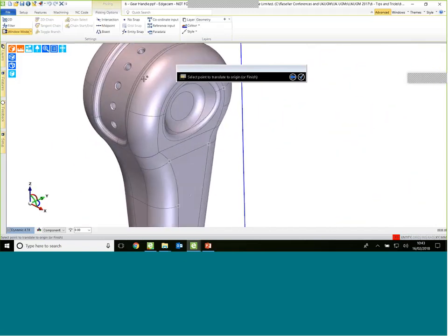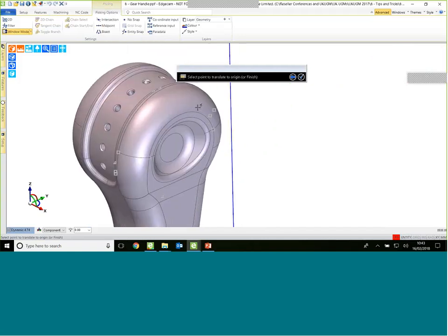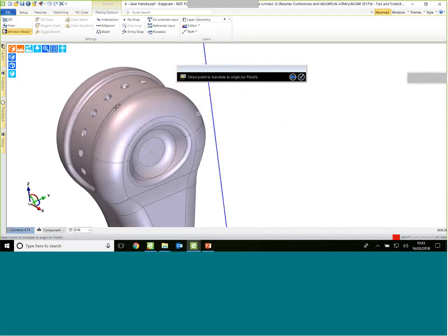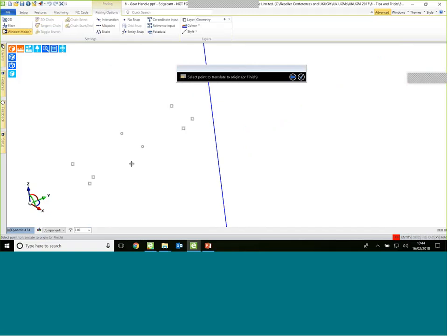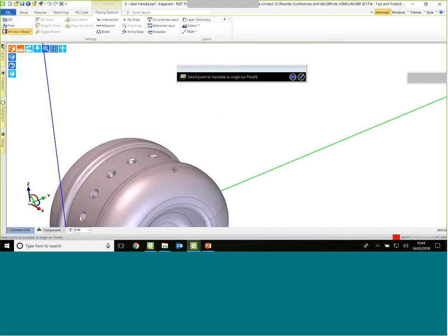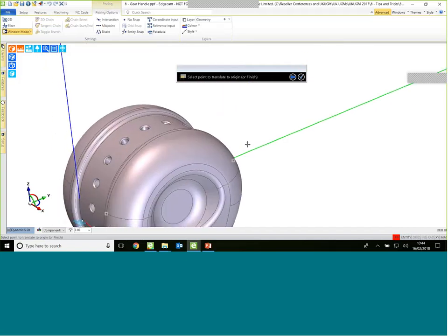It's quite annoying when you can foresee a hotspot. I'll just hang my cursor on screen there so you can see those hotspots. As I move my cursor towards it, it disappeared. So I want to try and get to a hotspot, or maybe because of graphics or whatever, that hotspot's beginning to disappear. A nice little tip or trick is, when you see the hotspot, hold down the F key on your keyboard. Now it doesn't matter where I go with my cursor, it will latch onto that position. I'll do that one more time. Again, I can see a hotspot, move to the hotspot, and it now disappears on me.